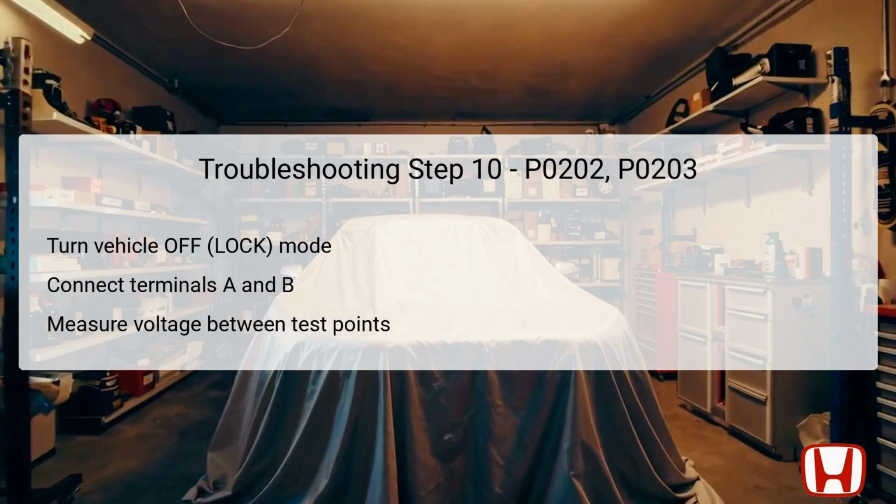With the vehicle in off mode, connect specified terminals in the injector relay socket and perform a voltage measurement using PCM connector pins. This checks for correct function of the INJ-RLY out wire. Finding battery voltage confirms effective electrical connectivity. If not, it indicates potential issues that require a detailed inspection for open circuits between these connections.